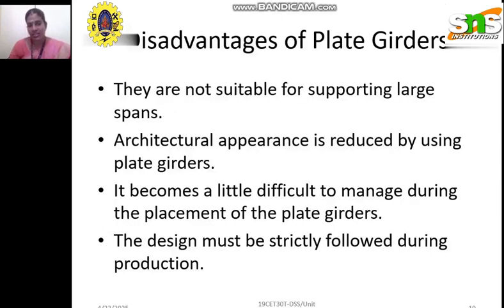If you are taking the disadvantages, for very large spans there are some limitations on spanning. If you are going for very large spans, this is not preferable. And the architectural appearance is somewhat less when compared to truss bridges. Also in some places the placing of the plate girder is somewhat difficult, and we have to do the design very strictly, and follow the codal provisions in a strict manner. Then only can we avoid failures.